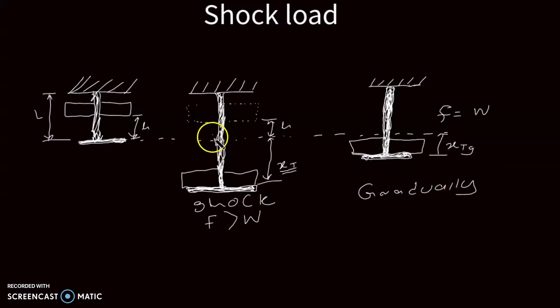This will be our change in length due to the gradually applied load. So if they ask you these questions, this will be the final change in length, and this will be the instantaneous change in length, because it was the change in length that happened immediately as the object came into contact with the rod. It caused the rod to come to this position, whereas after, due to the gradually applied load, it went back to this position. So this is the final change in length. Don't confuse those two.